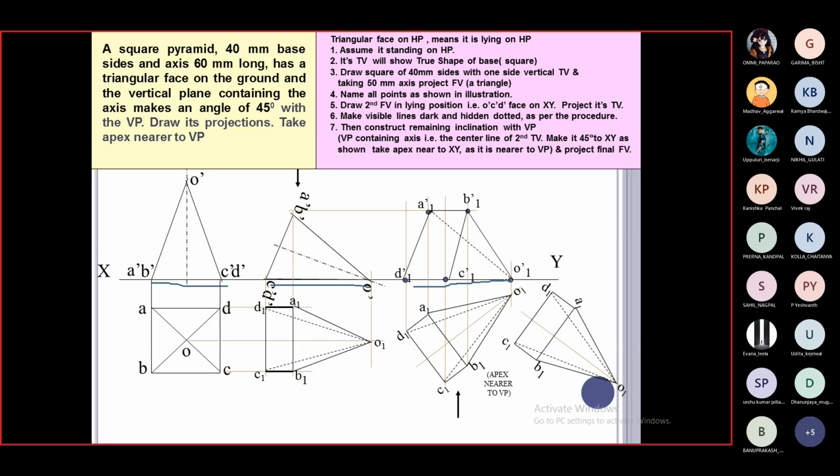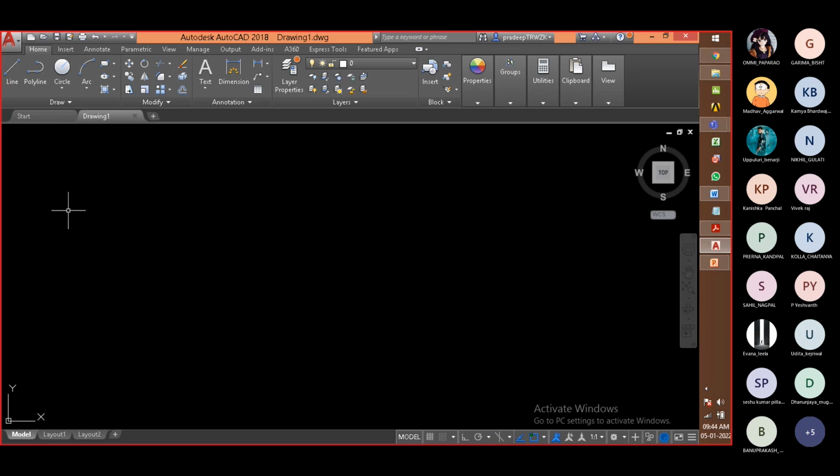160, and then we have to maintain a gap as per our required shape. So I'm going to maintain a gap of 30 between these sides and these sides. Okay, so around 160 is already there, and I'm going to add 60. So a line of around 220 length is going to be created. So I'm going to create a line of 220.